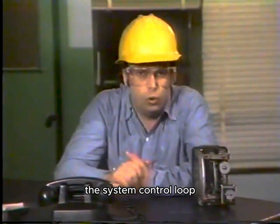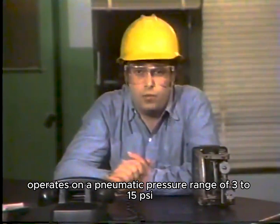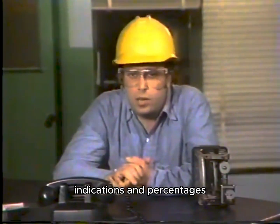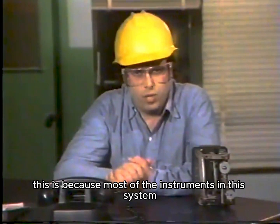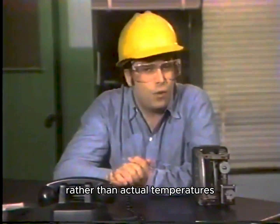The system control loop operates on a pneumatic pressure range of 3 to 15 psi. When tuning this system, the technician had to relate to both temperature indications and percentages. This is because most of the instruments in this system indicate percentages of the temperature range rather than actual temperatures.